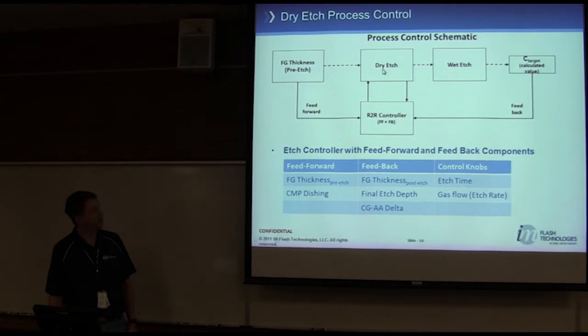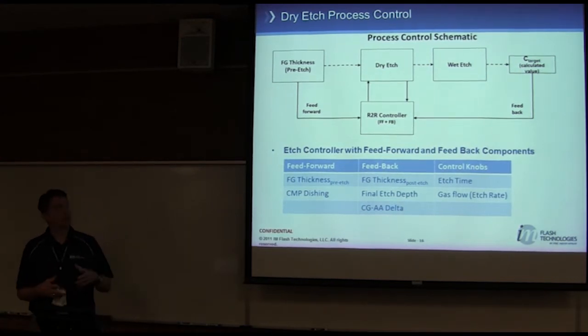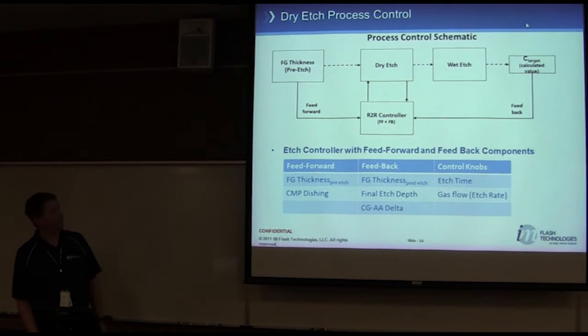So then you go through a dry etch step, and sometimes we go through other processing steps, wet etch or different other processing areas, and then before you get to post-metrology, we, again, as I mentioned before, make a decision based on how far off we were. Now, you guys talk about mostly continuous control, is that right? So you'll talk about milliseconds that always happens. This can be up to 12 hours by the time this measures till the time you hit here.